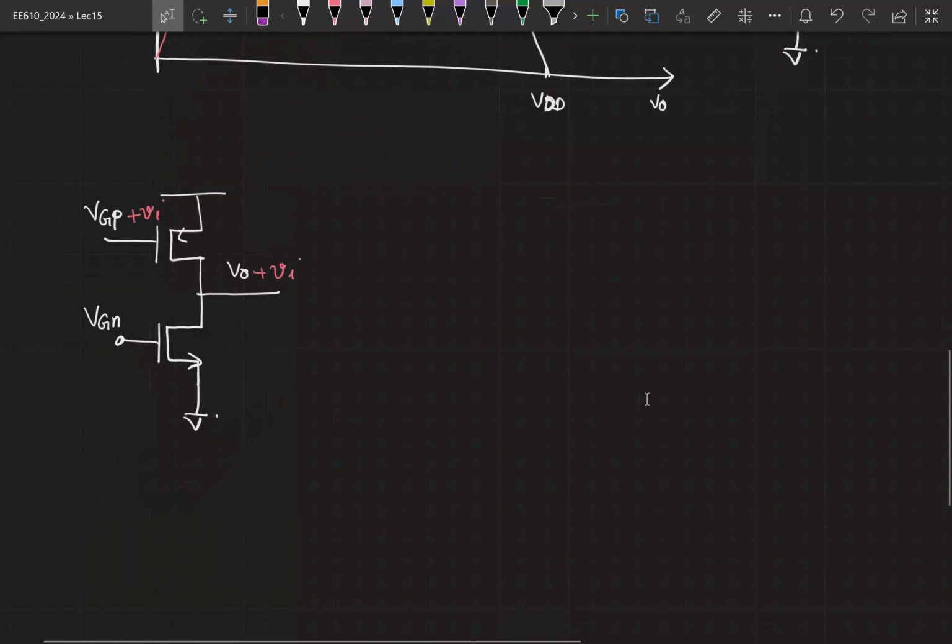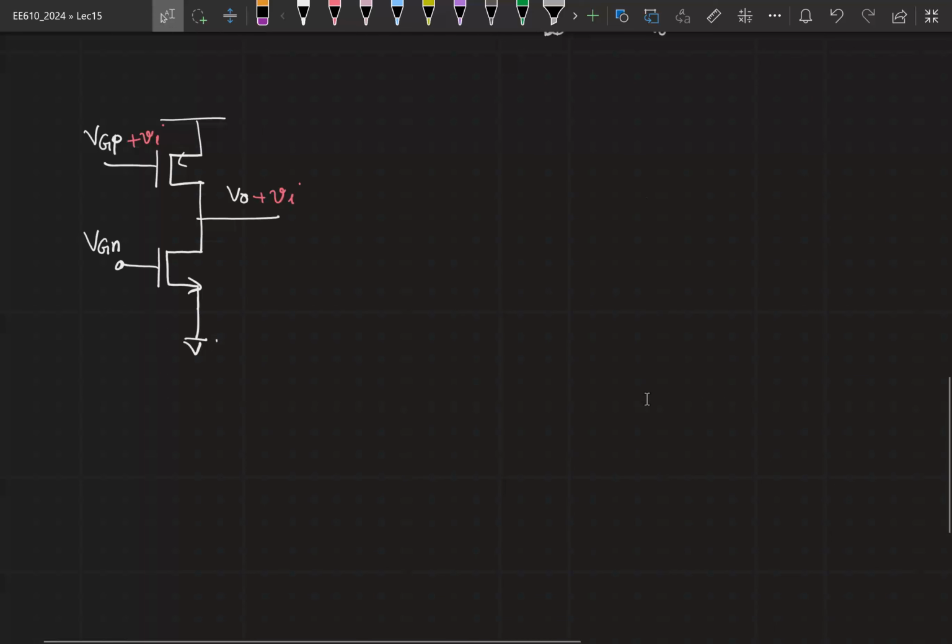Right, so this is the circuit we are working with. Instead of connecting a resistor as a load, now we have an active load. The NMOS transistor is not active per se, it is passive. But if you look at only the incremental picture, then it looks like an active device. Okay? And this idea of using a transistor as a load is very commonly used simply because fabrication of large resistors is also a little complicated, and this allows you to have a very large incremental resistance value even when you operate on a smaller supply voltage. So how does the incremental circuit look like?